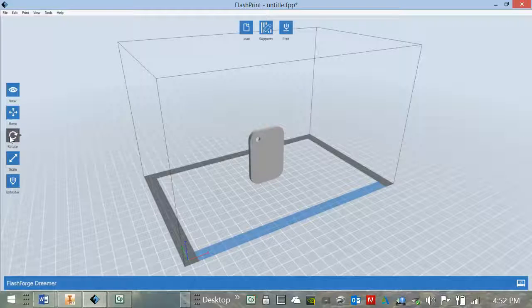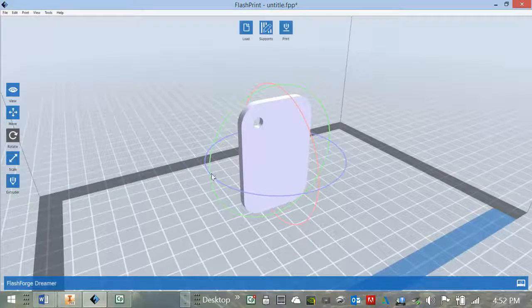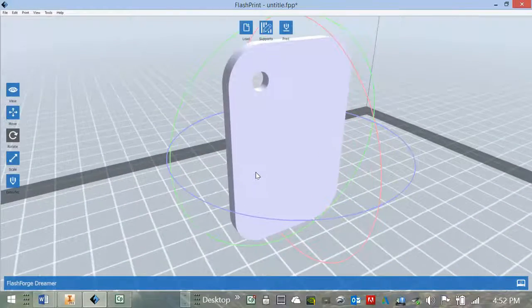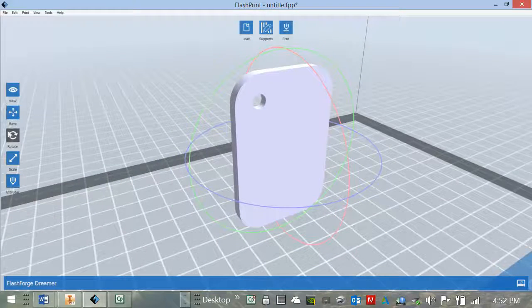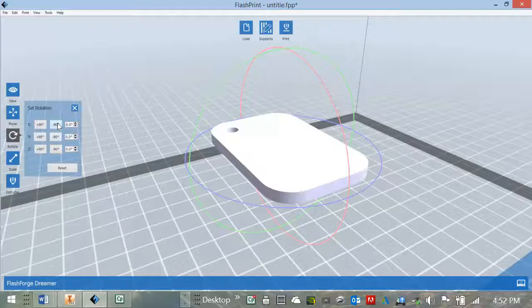So I left click on the rotate button here, another click again. It warns me that no model is selected. When that happens, you've got to left click and select this model. When it's highlighted like that in that lighter color, you're ready to start moving it. I'm scrolling in and out with my middle mouse button to create the zoom. Okay, so let's rotate it, left again. Now use the 90-degree movements to rotate around.